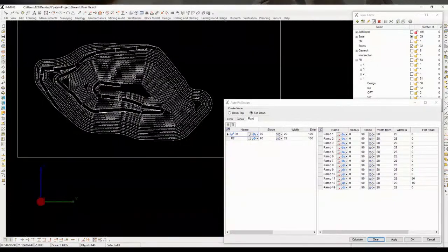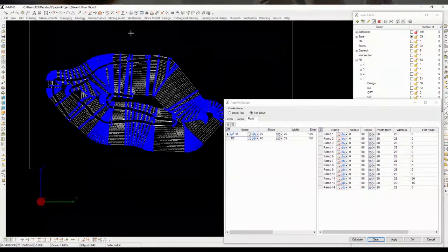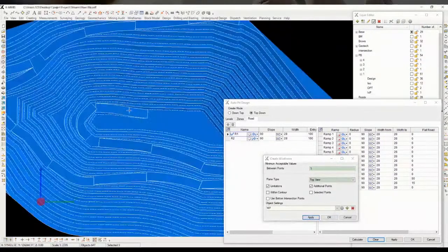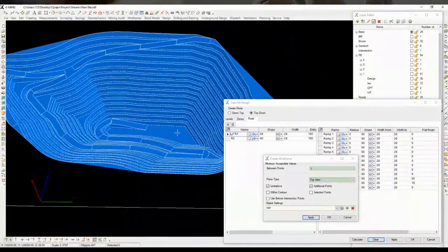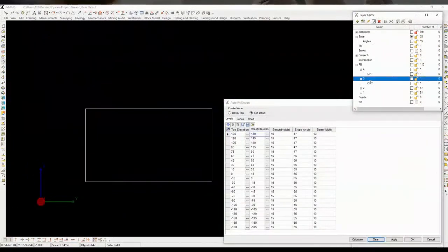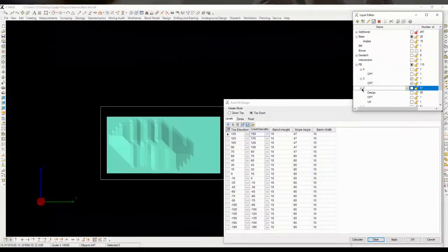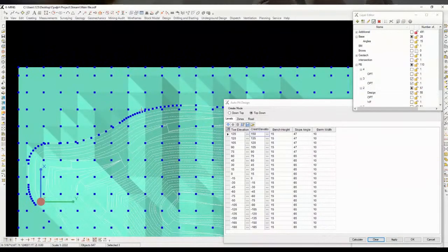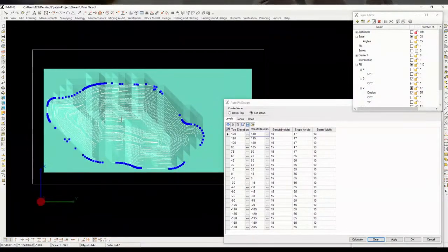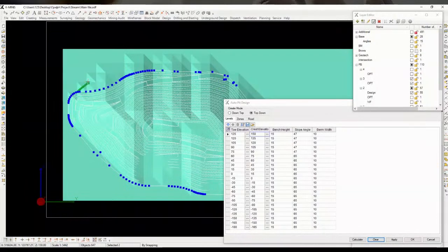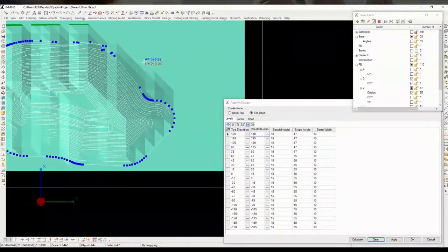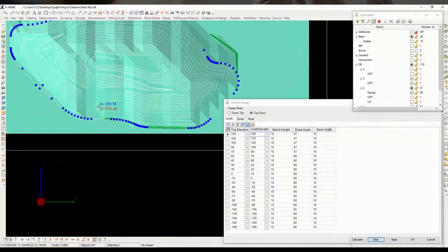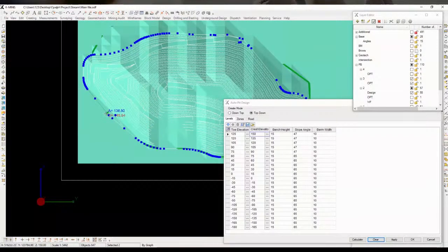And after that, we can start building the next pushback. Number 3, we will use a method similar to the previous one, building from the top edge, from top to bottom. By the way, if the user basically made an error and specified an edge that does not correspond to the horizon in the table, construction will start from the horizon marked in the table, but with the configuration corresponding to the selected line. And after we perform the same operations, we can proceed.